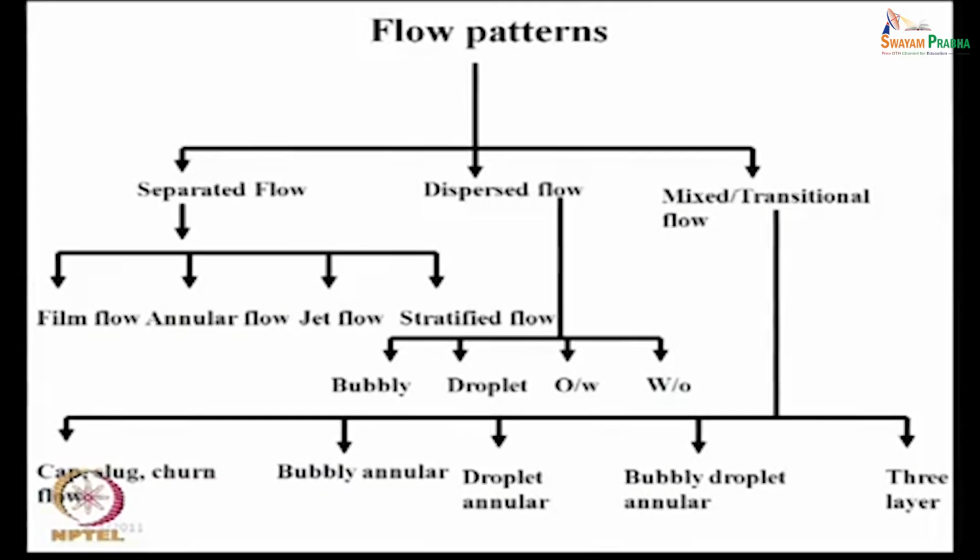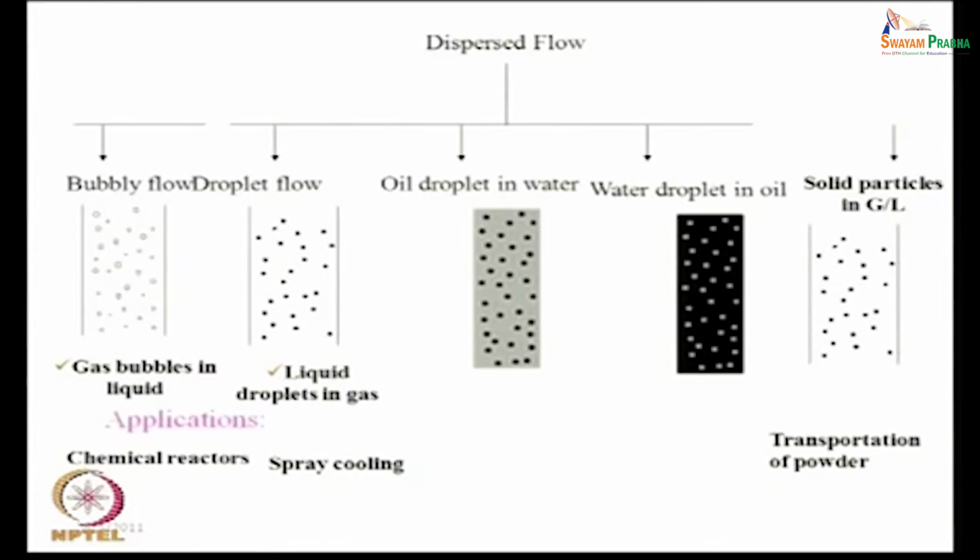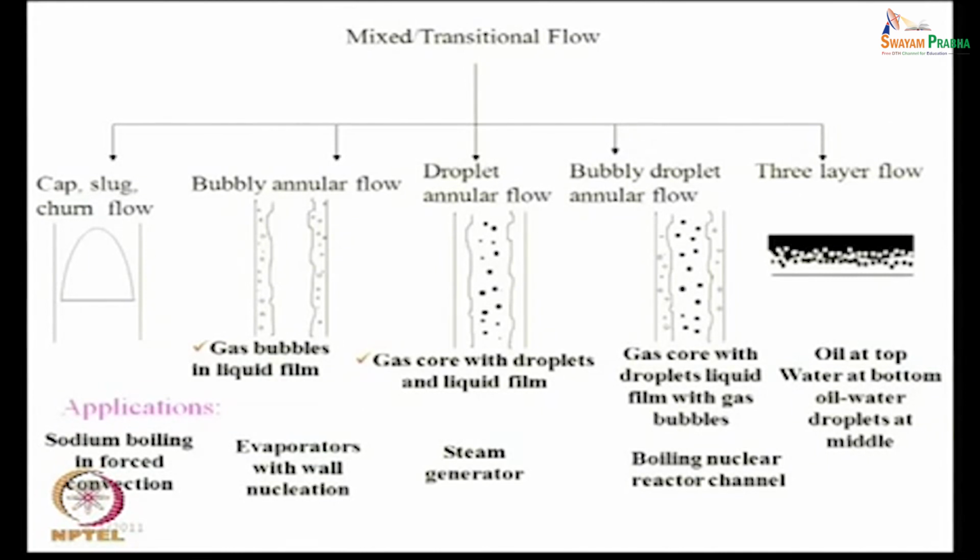Agreed, but the main problem is the transition zone. Same thing occurs for single phase flow as well, the transition zone, but the unfortunate situation here is that for most of the circumstances we operate in the transitional regime. Unless we go for very high velocities or very low velocities, we are mostly operating in the transitional flow patterns, and we find the range of flow patterns covered by the transitional circumstances. So, therefore, after the flow patterns, the next thing here we have is about where dispersed flow occurs and the industrial applications of this type of flows, etc.